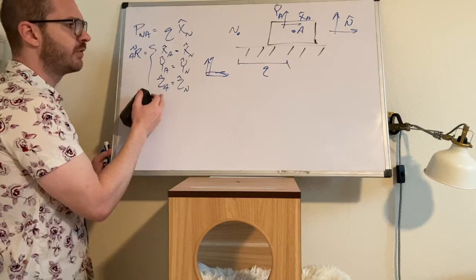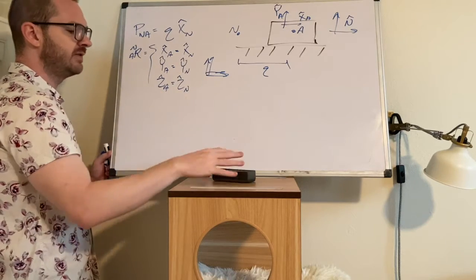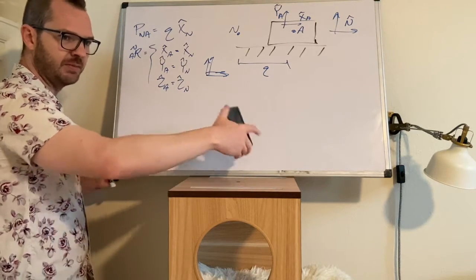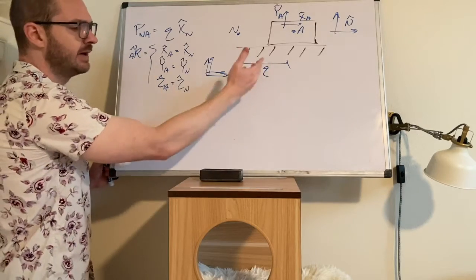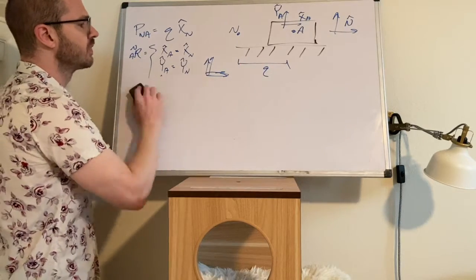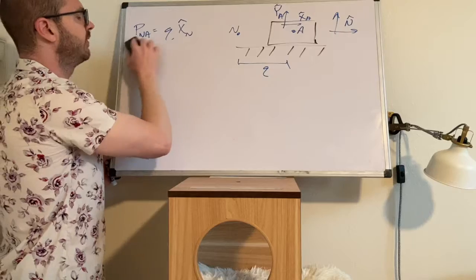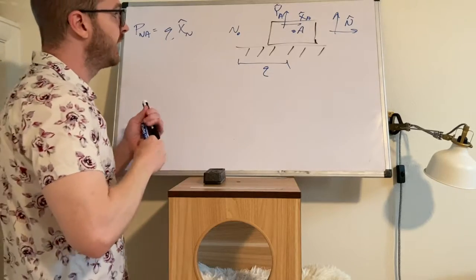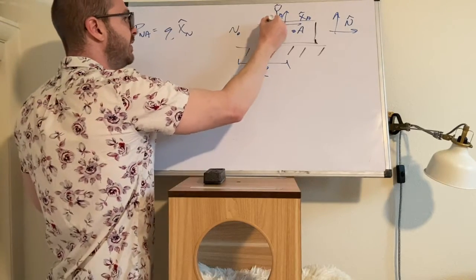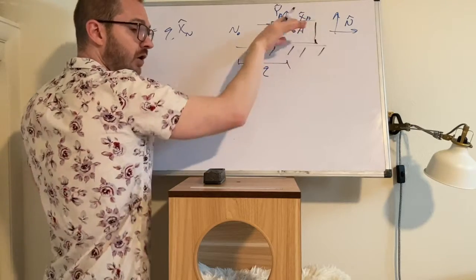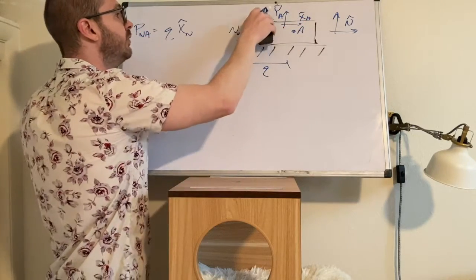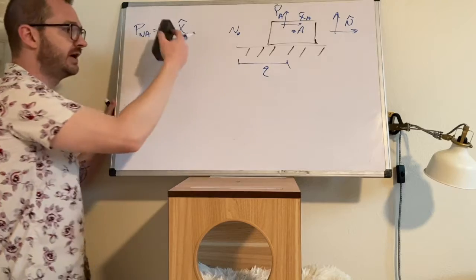The fact also that we define that there is no rotation means that this block isn't ever going to tip. We haven't added any tipping into the definition of the problem. If we were perhaps applying forces, which we will do later, at the top corner that may cause this thing to tilt, then we would have to define some rotation in the system.